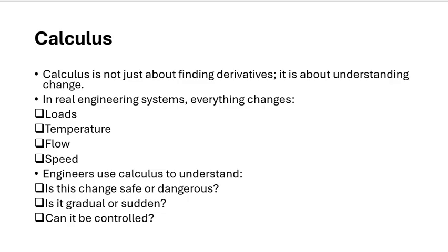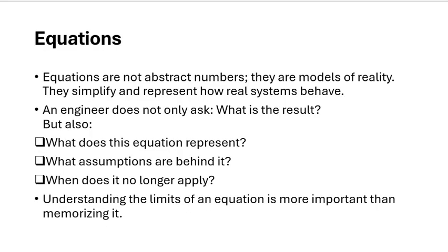Got it? Clear? Okay, and by the way, the problem is the heat exchange is very fast. With cement, the heat exchange is very fast. That's why we need to keep it wet. If it was slow, then it would happen automatically in the environment. If something is generating a very low amount of heat, it will automatically dissolve in the environment, no problem. But the heat exchange is very fast. So because it is fast, I need to control it. If I don't control it, I will start seeing cracks. Got it? So all these things are related to change and they come from the concept of calculus.